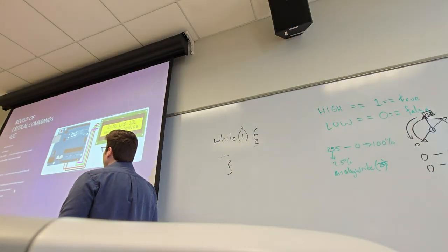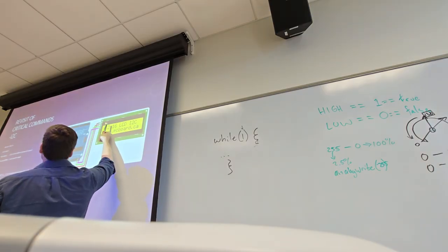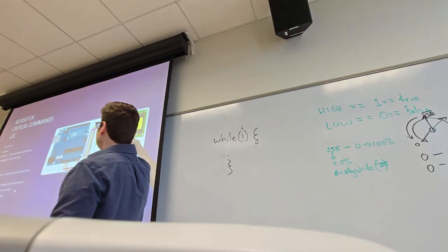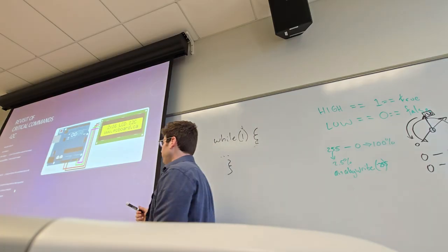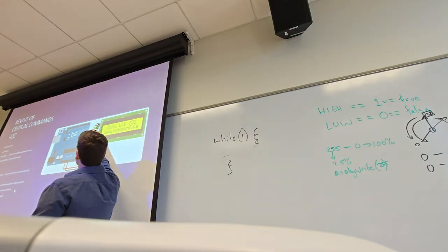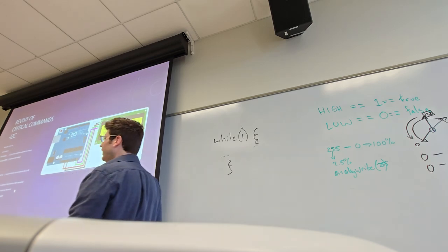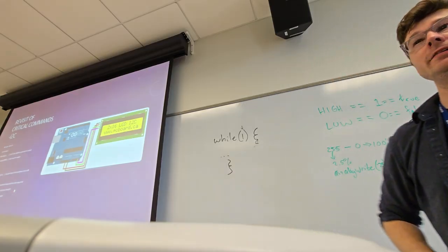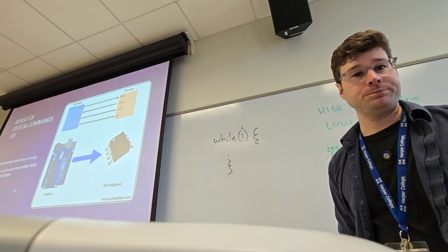I²C sensors aren't necessarily sensors. They can also be command devices. Motors can be commanded. Heaters can be commanded. Displays are very often I²C. You can do some pretty complicated stuff with it, and only with 4 wires. Our ground connection, our power connection, and SDA and SCL are always the pins for I²C. When you see SDA and SCL, you're dealing with an I²C sensor.